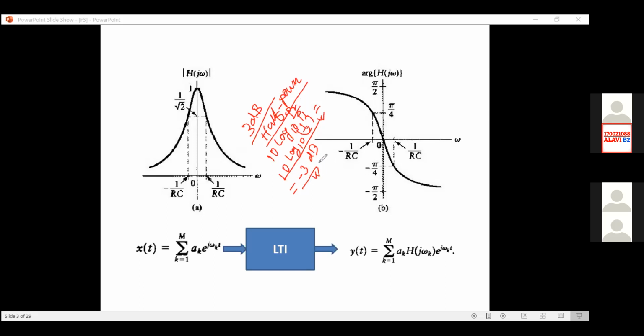If it is -3 dB in terms of power, then the H omega that we are having, this is a very intuitive explanation. The magnitude of H omega we are having, is it related to power or to your voltage or current ratio? Sir, power. How can you say that it is power? Because we are obtaining this by using this ratio y divided by x. Is it power? No, sir. Are they not voltage?